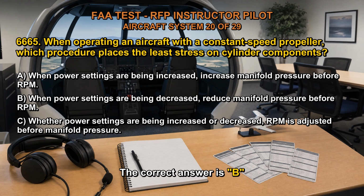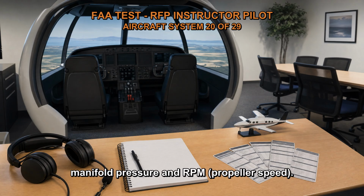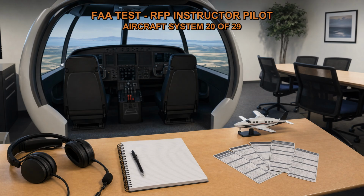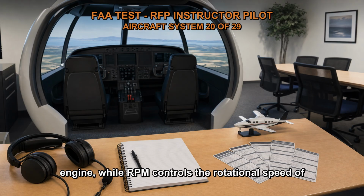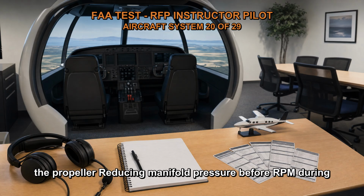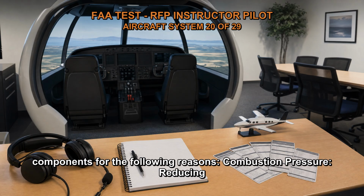The correct answer is B. In an aircraft with a constant speed propeller, the pilot has the ability to independently control both manifold pressure and RPM, propeller speed. Manifold pressure represents the power output of the engine, while RPM controls the rotational speed of the propeller. Reducing manifold pressure before RPM during power reductions helps to minimize stress on cylinder components for the following reasons.